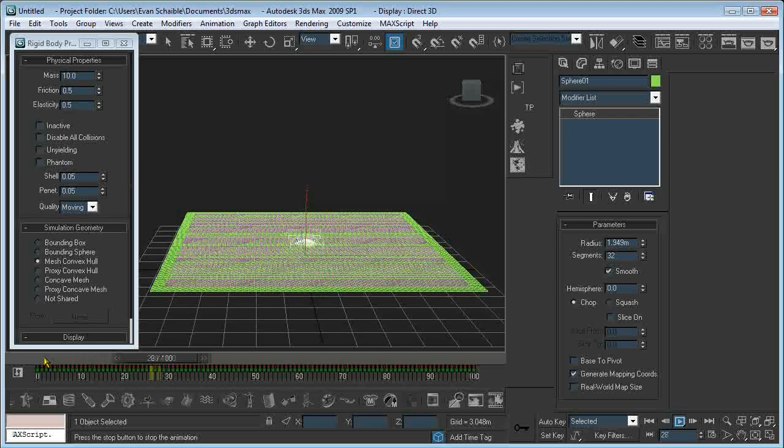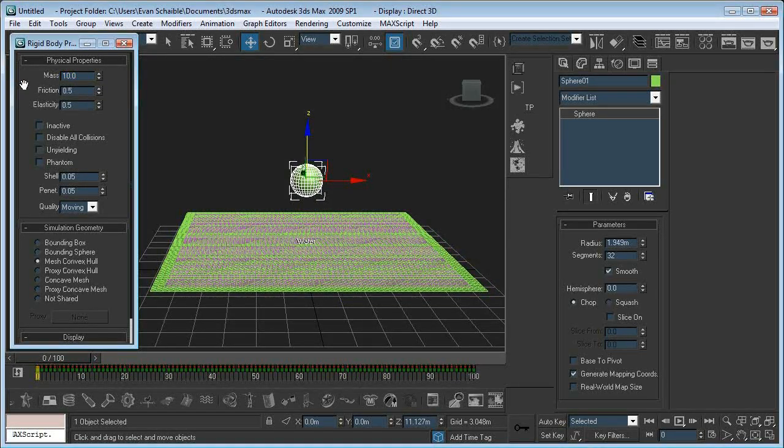Pretty close to the same concepts. So you can see it looks pretty realistic, and it sinks down, pops back up. We don't get any splashes because that's a whole other tutorial, a whole other system in and of itself. But it looks pretty nice as we have it right now. So that's the reason it sinks down and bounces up so much, is because our mass setting is about 10 times higher than the density setting of our water.